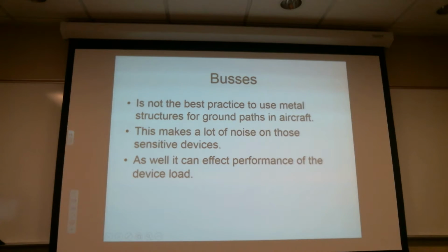If you have a lot of really weird stuff going on, like you open the door and the wipers come on, oftentimes it's a ground plane issue, something on the ground side. So what happens is electricity goes, well, I'm used to going that way to get back, but I can't, so I'm going to go back through this circuit this way. Is that what's called a ground loop? Can you explain a ground loop?